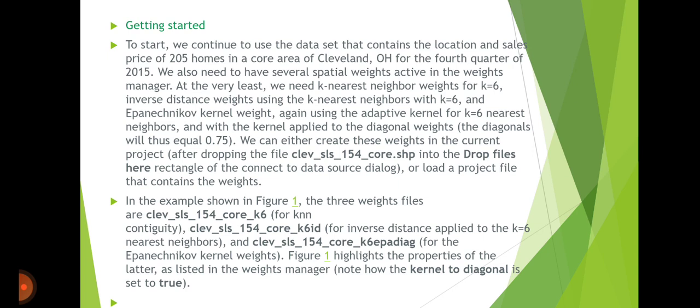We can either create these weights in the current project after dropping the file clev_sls_154_core.shp into the drop files rectangle or connect to data source dialog, or load a project file that contains the weights.